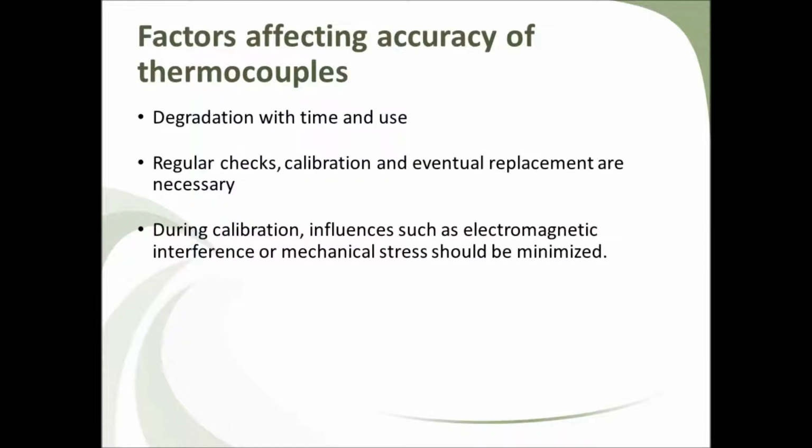With time and use, degradation of the thermocouple and its calibration is inevitable. In the long term, therefore, a scheme of regular checks and eventual replacement should be established and maintained. When the calibration is carried out, it should be ensured that effects due to influences such as electromagnetic interference or mechanical stress are minimized.